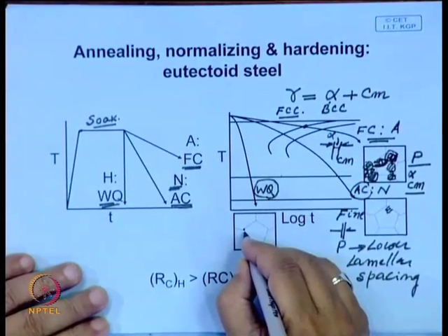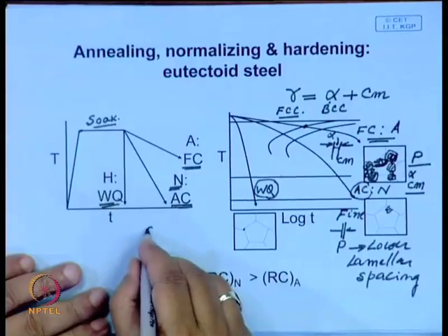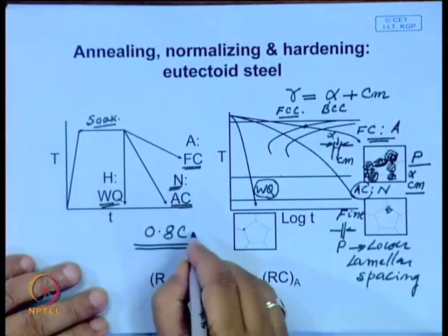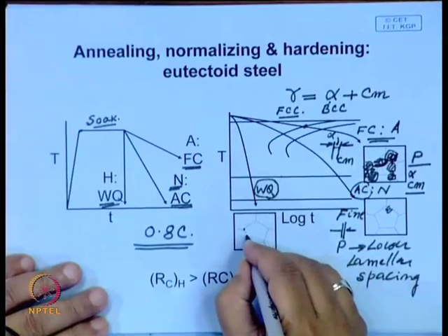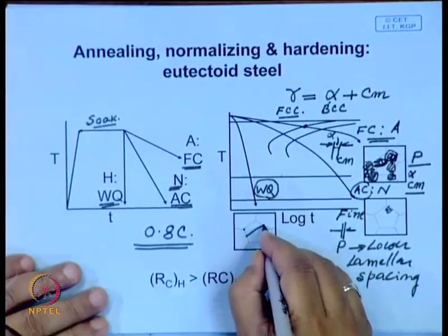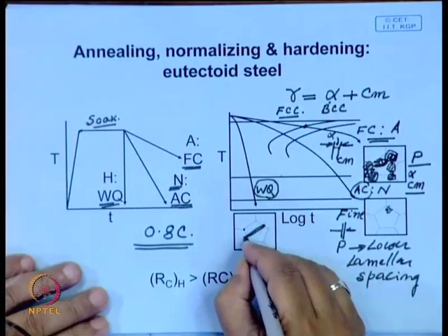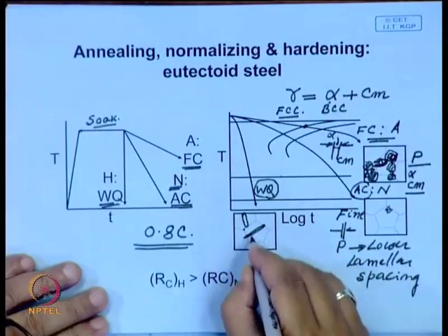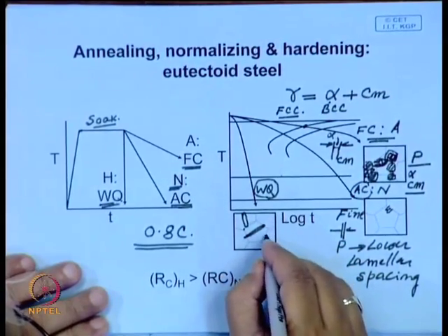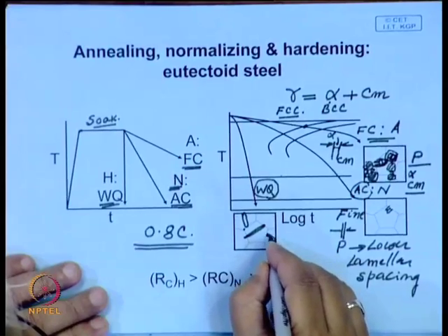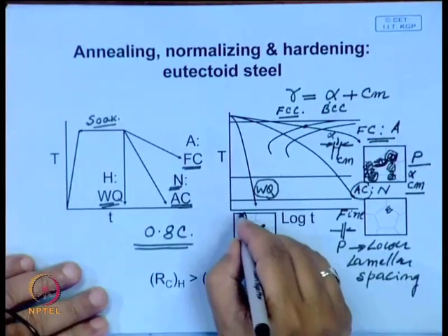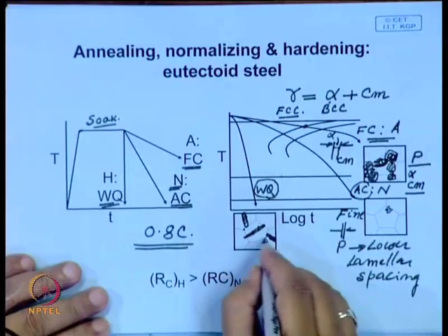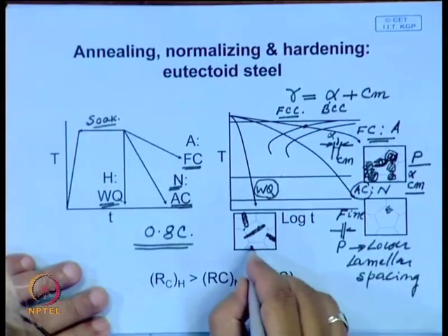We looked at its characteristics, and in the case of a eutectoid steel the carbon content is quite high, 0.8% carbon. So, here what you expect is a plate type of martensite. These martensite plates will be made up of very fine micro twins, which it will not be possible to detect or see under an optical microscope.